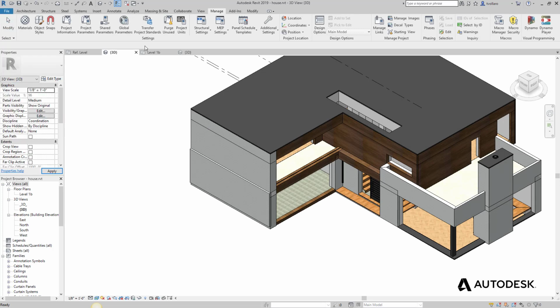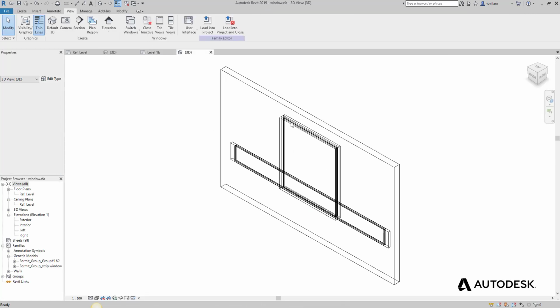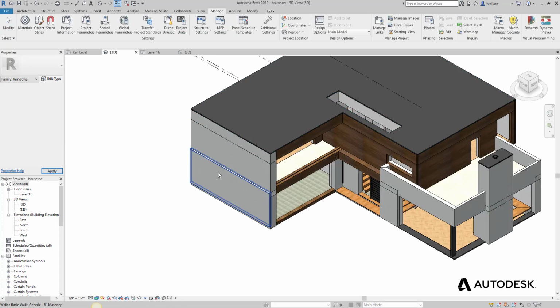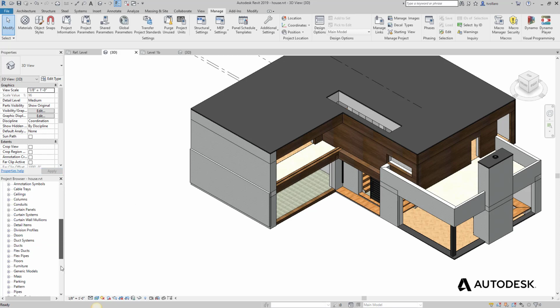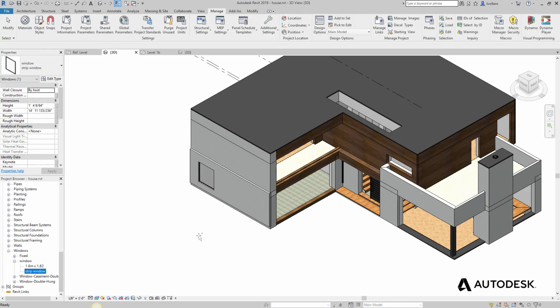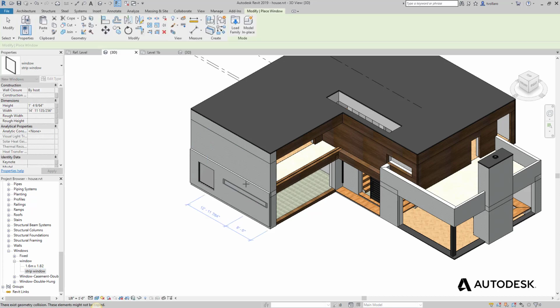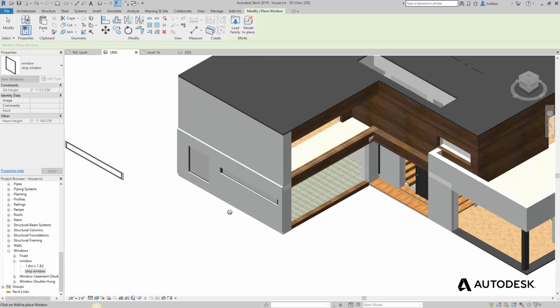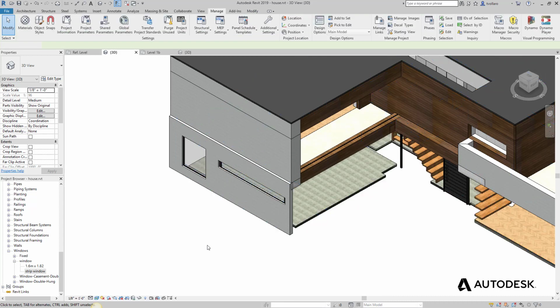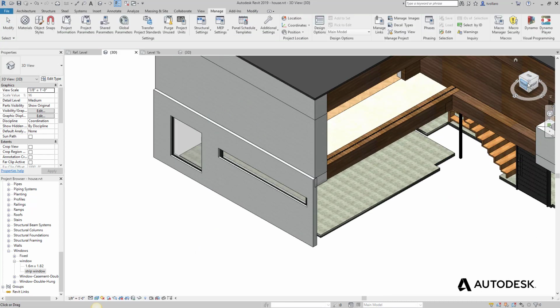And then the last thing I want to show is you can actually import geometry from FormIt into a Revit family. So in this case I have a window family, and we've imported some of those windows from that SketchUp file into this family and created a couple types. So now if I load this into the project, I can place these windows, and they're actually cutting the geometry.